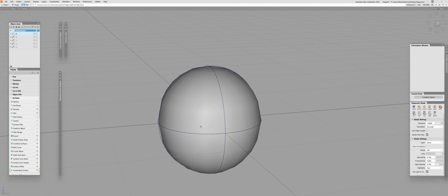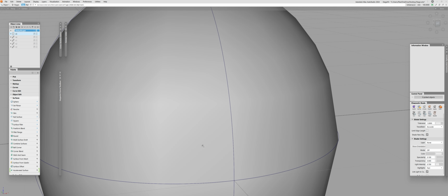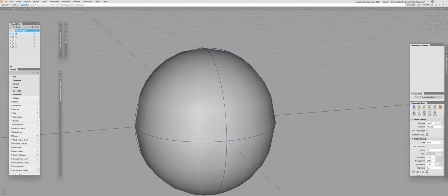And the third is polygonal approximation. These points evaluated in step 2 are then connected to form a mesh of polygons, usually triangles, but not necessarily. It depends on the algorithm. Now, this step approximates the smooth NURBS surface with a piecewise linear surface, which is a tessellation process, basically.